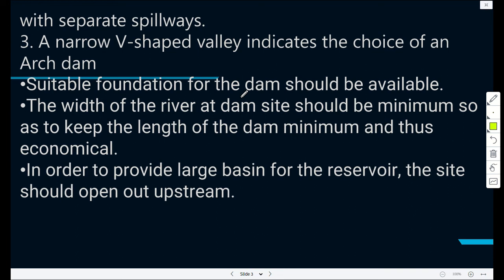Most of the time, you do very detailed site investigations, because you can imagine if a dam fails, then the entire city downstream, or the people living downstream, are most likely going to die. So you need to be very careful. When doing the site investigation, you have to map any kind of fault in detail, and you need to know how many faults, how many lines of weakness, we have under the foundation.